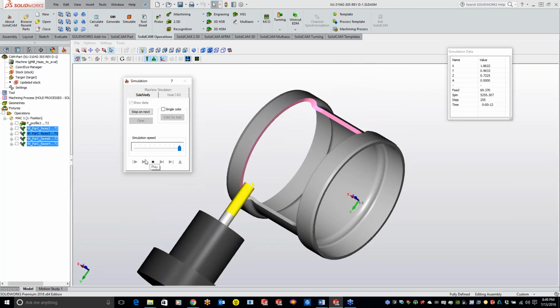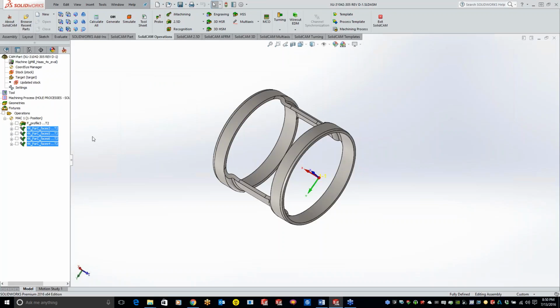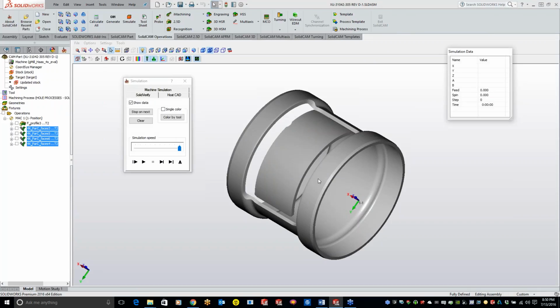So it's a real nice feature for you guys. If you have a piece that you slugged off, all you have to do in your Solid Verify is click on this guy right here, and if you have 10 different slugs, it's going to show you 10 different models of what you want. Just click on the one you want, right-click, and delete. It's just a temporary delete inside the Solid Verify, so if I exit out of here and redo a simulate, it's going to show back up. It's just a temporary little fix for you guys.